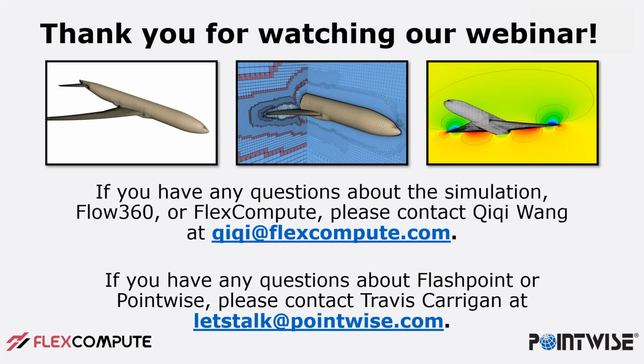And we also recently developed a rotating interface. So basically, if you have a propeller rotating within a bigger mesh, or even things rotating within something that rotates, you would need a cylindrical enclosure of the rotating mesh within a bigger mesh. Yeah, that's the kind of mesh requirement we have. Okay, and there was a question about modeling props, and I think that also answers it as well. And there was an example of that too.